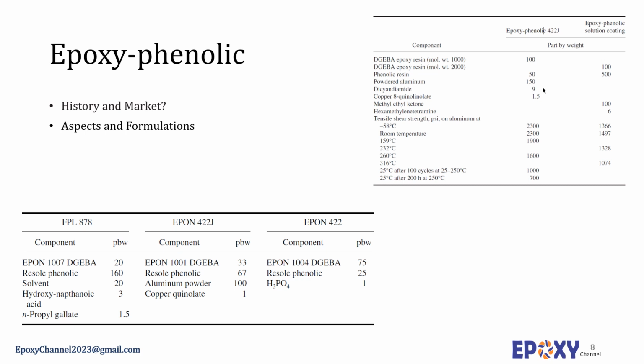The current trend in formulating epoxy phenolic adhesive is to increase the epoxy content for greater toughness and toward using acid accelerator for faster cure. Epoxy phenolic adhesives are generally preferred over other high temperature adhesives such as polyimides and polybenzimidazoles because of their lower cost and ease of processing.